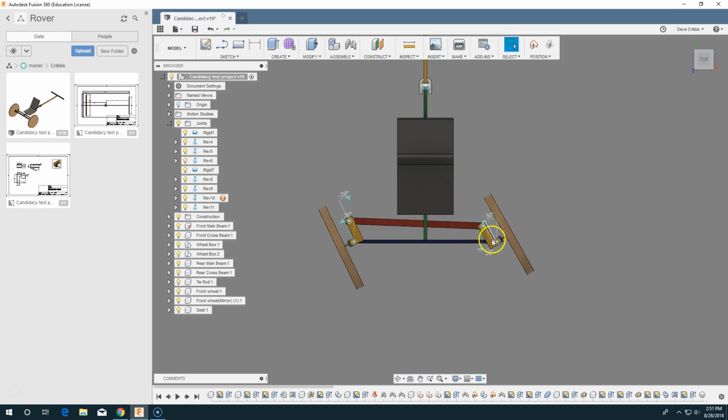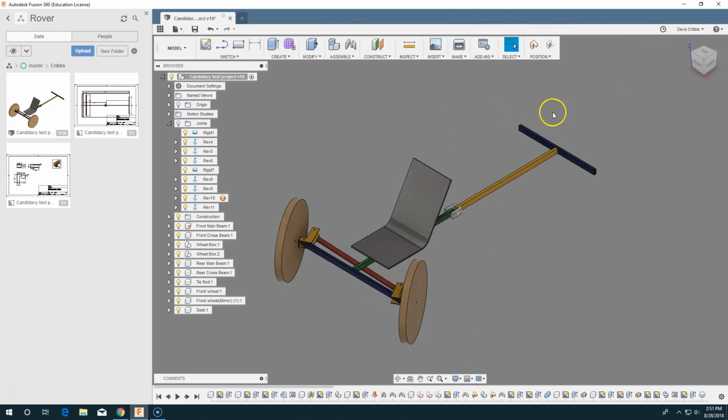The angles for the inside wheels, 30 and 32, are greater than the angles for the outside wheel. So the inside wheels need to turn a little bit sharper just so that it steers better. In this video will help describe, and in subsequent videos will help describe how to create a CAD model with those kind of properties. So I'll just revert this back and leave this.